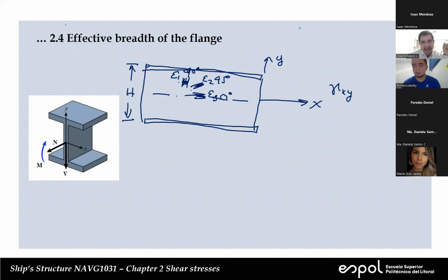But we can assume that they are more or less in one single position, measuring the strains in the 3 directions. If we use a larger section, the error because of this difference will be smaller. But the problem is we will have to apply a larger force, and I don't want to do that. So yes, we have to assume that they are in the same position.